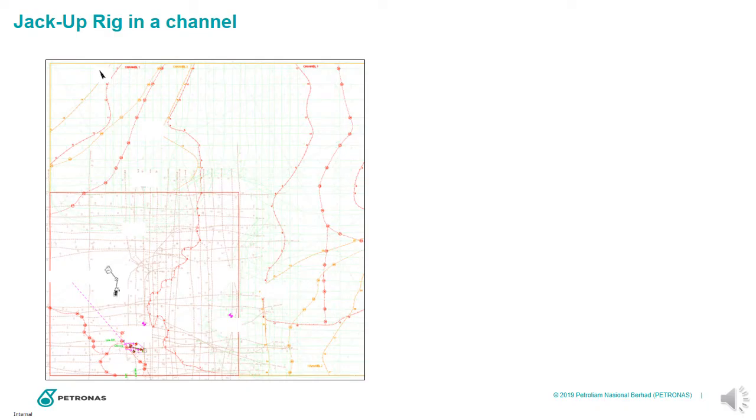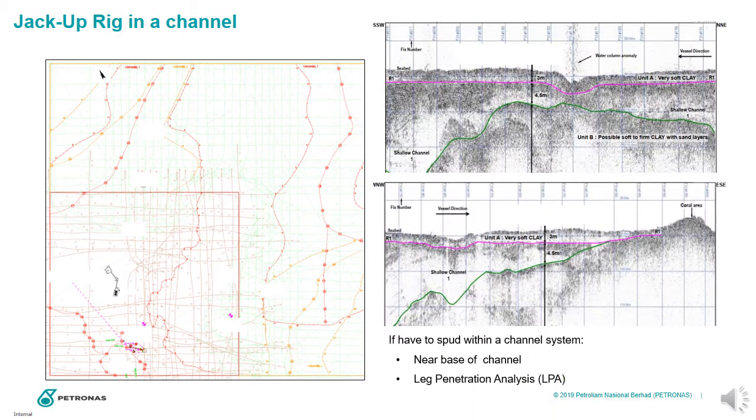Is it safe, and has it been done before? Yes, it is actually relatively common and acceptable, but if we had to put it on top of a channel, it's generally advised to put it near the base of the channel and have leg penetration analysis done.